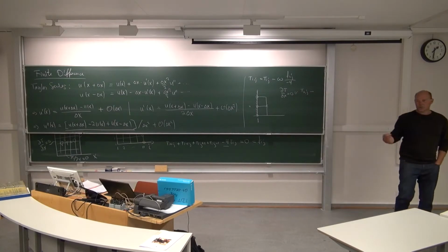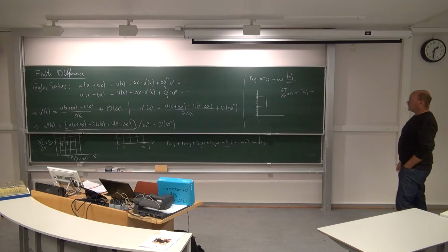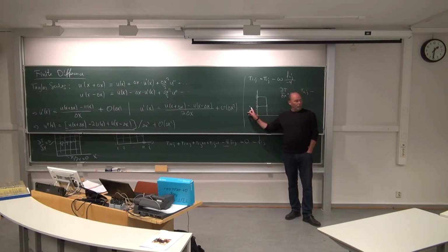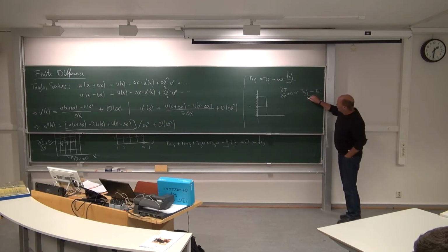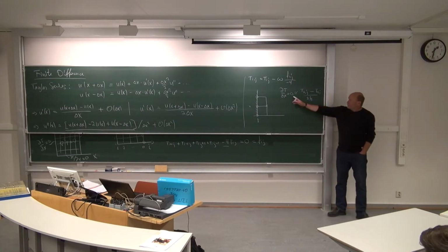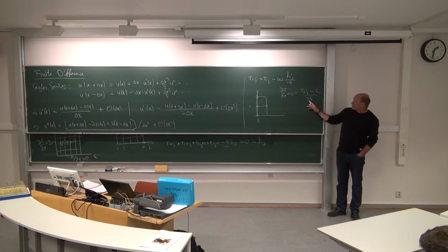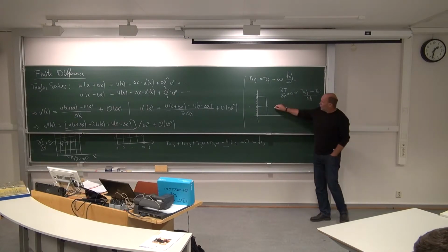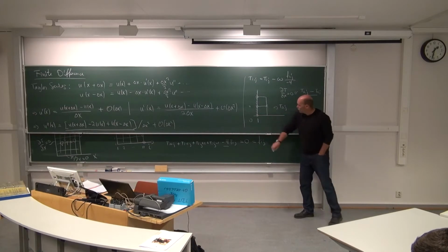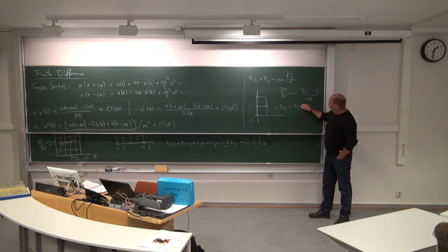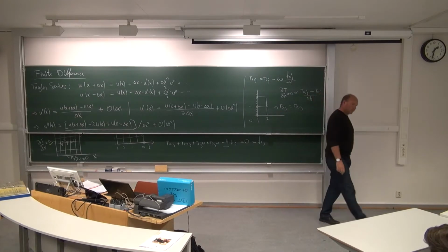That's a neat trick. You use ghost cells inside the wall. They're not real, but very convenient if you want to use them for boundary conditions. So I invent a fictitious value inside the wall. I call it T 0 j, divided by 2 delta x, or 2 h's, was it now? Like that. Well, if it is supposed to be 0, you can multiply with 2h, and then you say these two have to be equal, meaning this strange value I have inside the wall, number 0, equals number 2, the one we have here. So that's very easy.